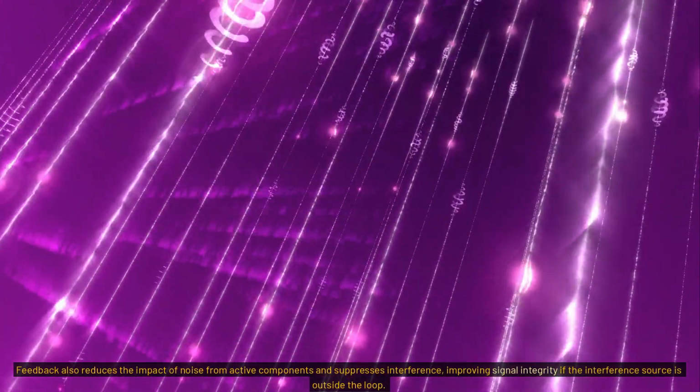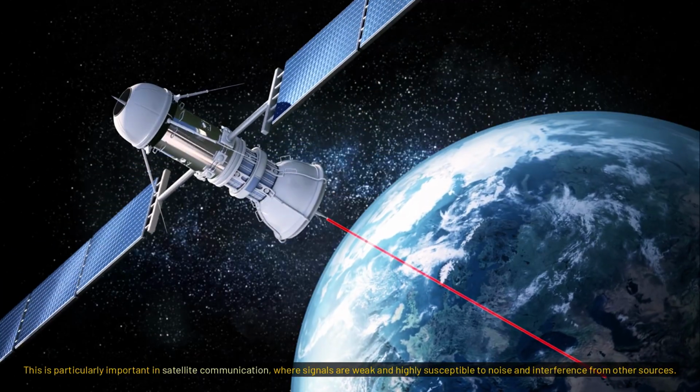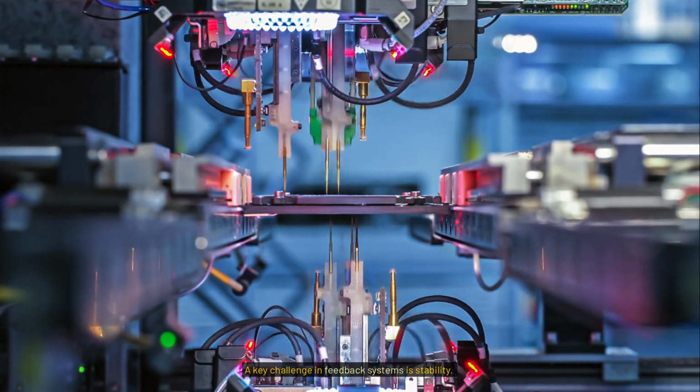It reduces nonlinear distortion by lowering signal amplitudes at active device terminals, improving linearity, and reducing harmonic distortion. In broadcasting equipment, reducing distortion is crucial for delivering clear, high-fidelity audio and video signals. Feedback also reduces the impact of noise from active components and suppresses interference, improving signal integrity if the interference source is outside the loop. This is particularly important in satellite communication, where signals are weak and highly susceptible to noise and interference from other sources. A key challenge in feedback systems is stability.